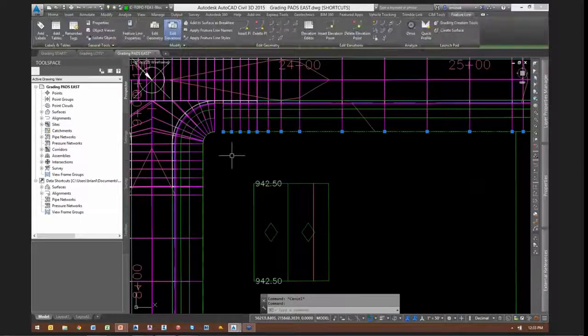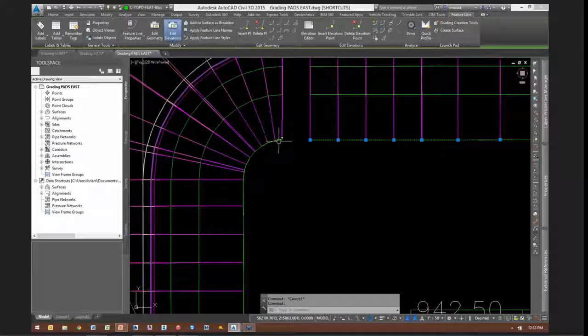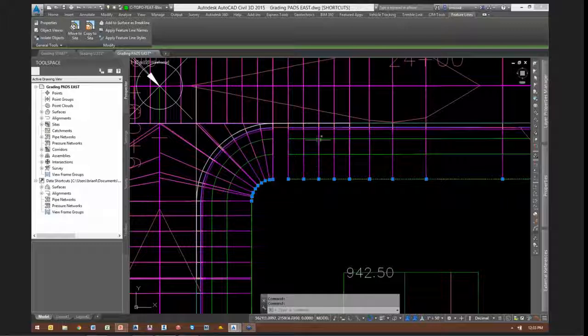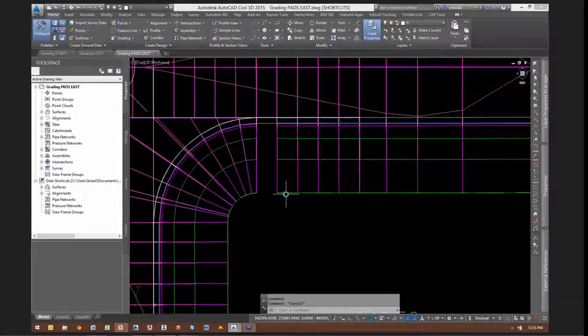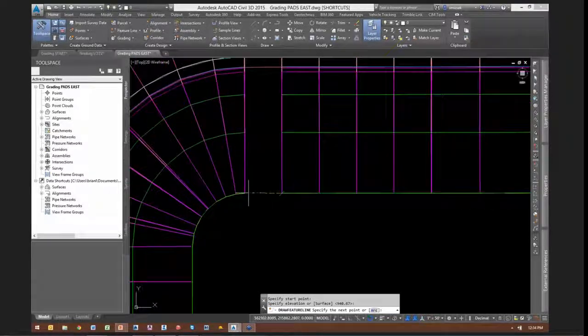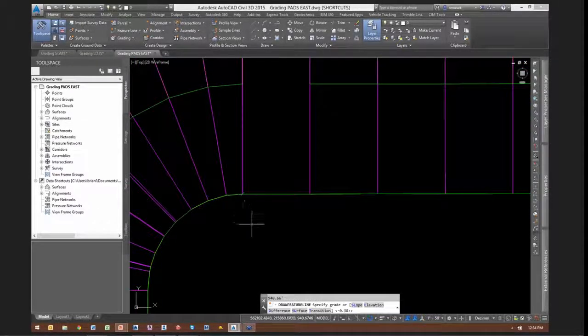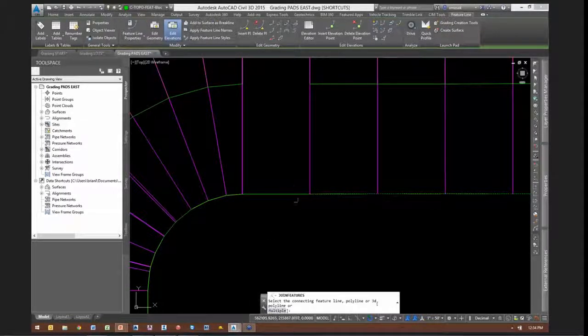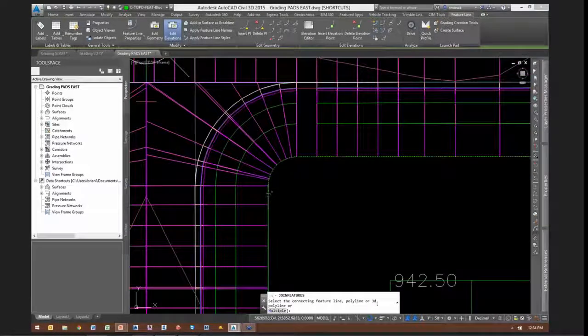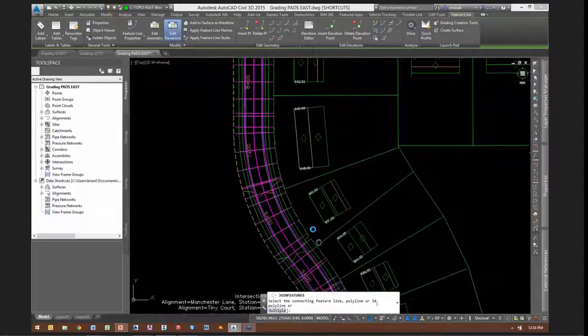And then what you're going to notice is that some of these don't touch. Occasionally, with the intersection tool, this is the way it builds. It's contouring fine in there. What we end up having to do is add a couple extra pieces in here. In this case, I'm just going to draw a feature line manually and connect these two points. Then I can start joining these. So join that one to that one. Keep joining these all the way around here.